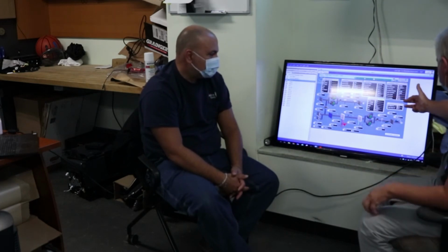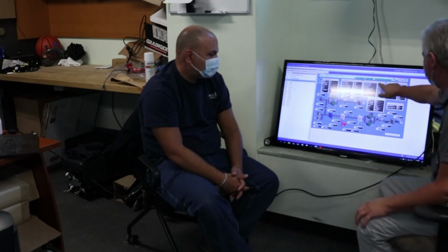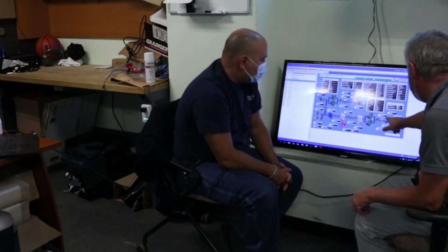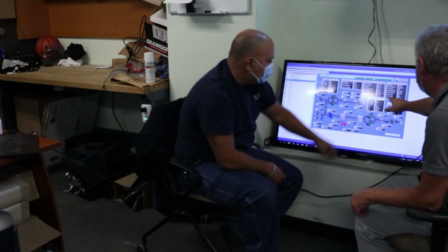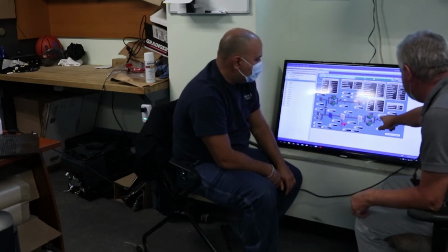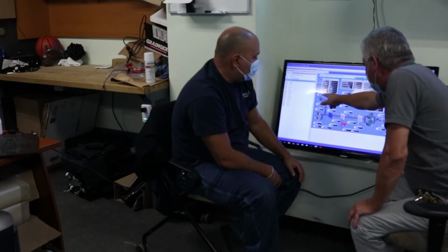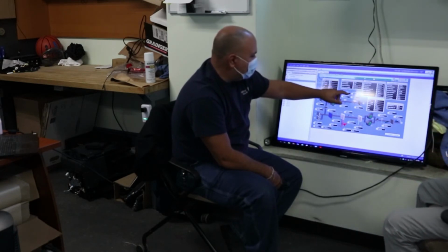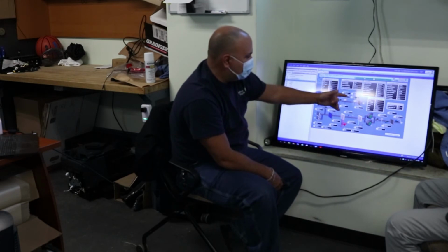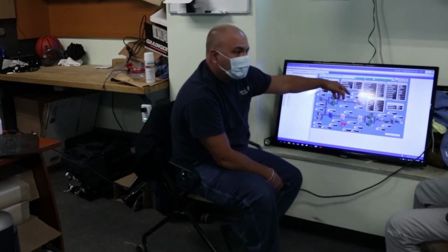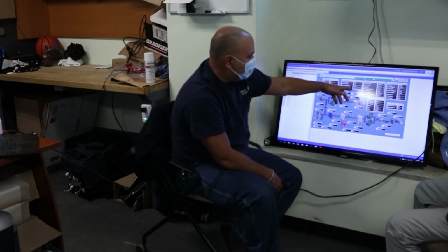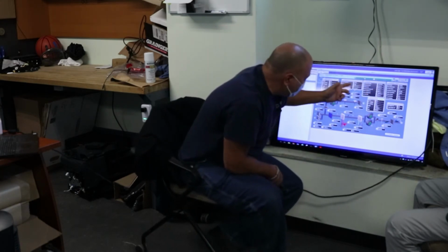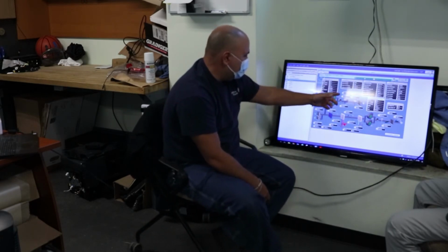Cooling is unavailable now, and outside is 63, and the discharge temperature set point is, well, you're looking for 53. But we have 65, and that's why we have outside air. What it's saying is it does enthalpy, outside air versus return air enthalpy. Since the outside air enthalpy is lower, we're going to bring in the outside air. You don't have cooling available, so it's better to take the 70-degree air from outside, 69, than to bring back the 73 return air.